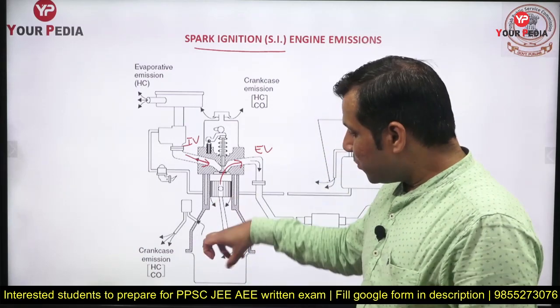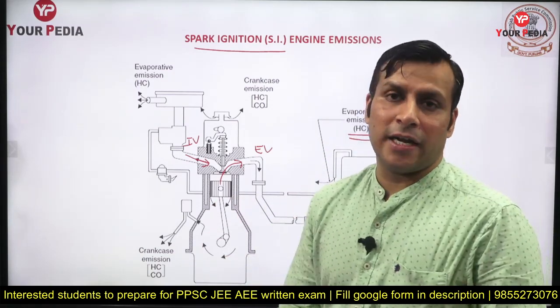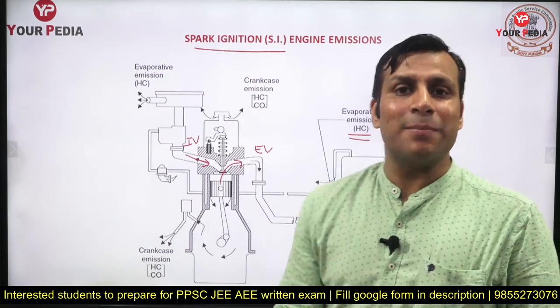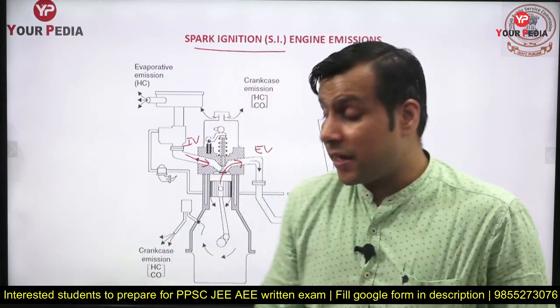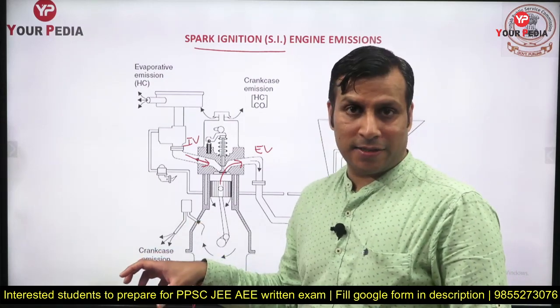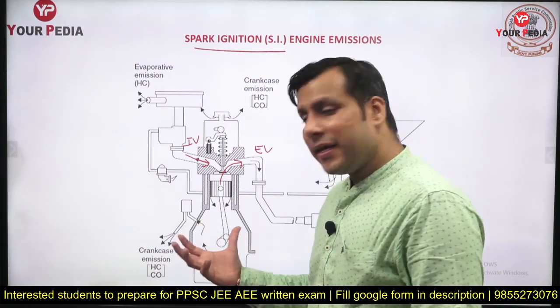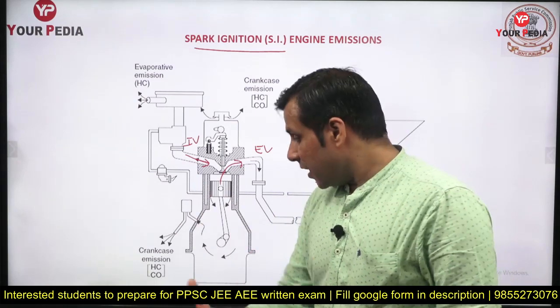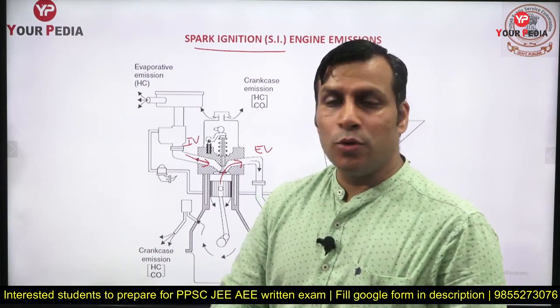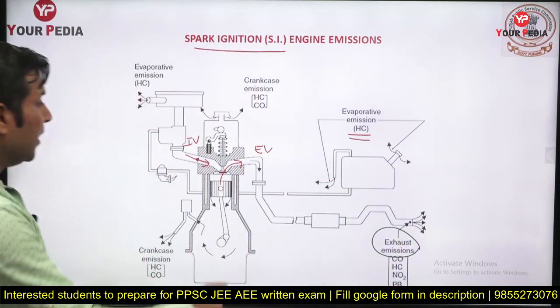Guys, when they leak into the crankcase, two major effects we can get. One, if a very high concentration of hydrocarbon leaks into the crankcase, then some kind of crankcase explosion can occur. If a huge amount of hydrocarbons leaks into the crankcase, they can combust in the crankcase. That is known as crankcase explosion. Otherwise, when hydrocarbons enter the crankcase, they are going to mix with the lubricant and dilute it. That is also an effect which we are going to observe, majorly due to the blow-by.